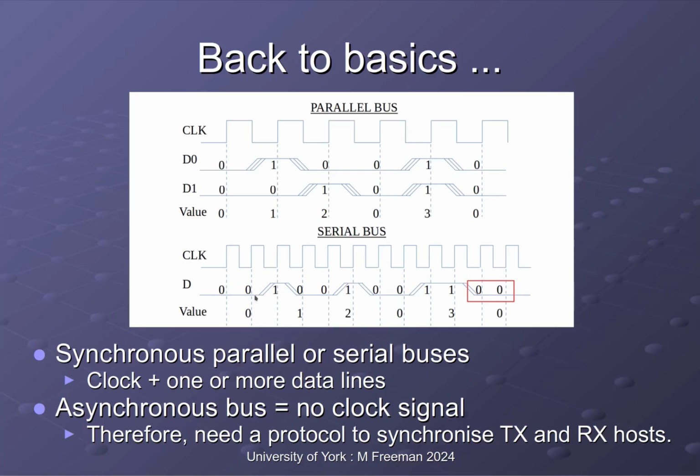It won't be a value that is changing from one state to the other state, because obviously that would be dangerous. That would be a bad idea. You only want to read your data when it reaches a stable, a consistent value. However, to save some wiring, that's what we do on our networks. We go to asynchronous buses. So now the problem becomes, how do I regenerate this clock signal on the receiving end?